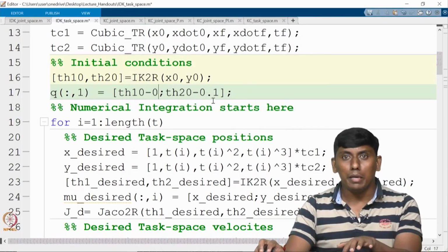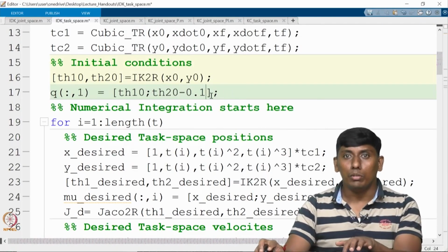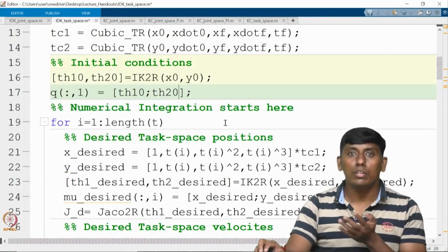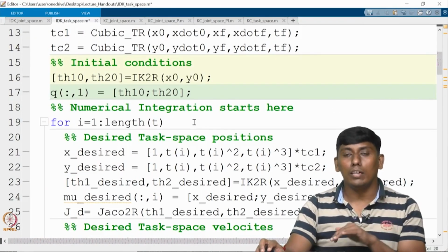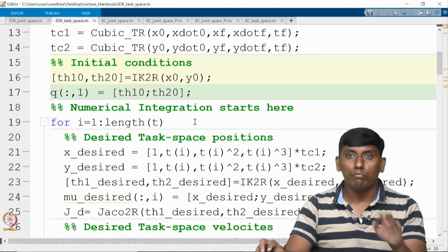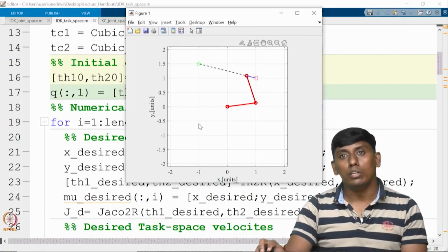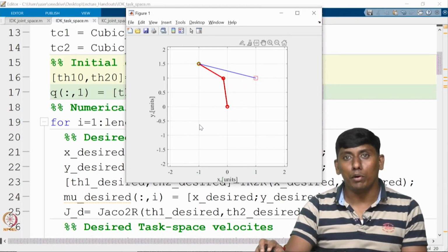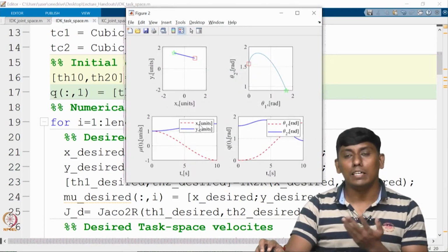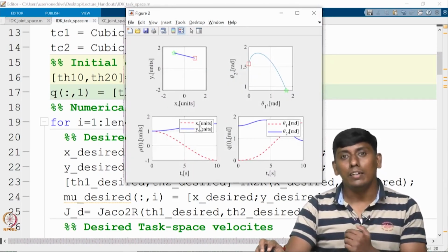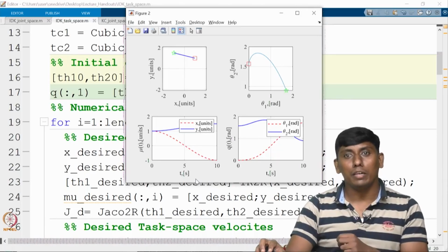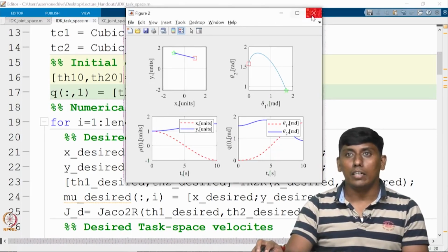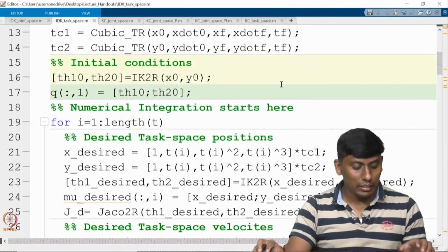So now, the condition you have seen is this, right. If the velocity is non-zero and the initial actual and desired positions are the same, then you will find that this would be a good control. That is why we call it open loop control, because it is feed forward, right. There is no compensation for the actual case. So even if I introduce a small friction or some kind of uncertainty, it will not follow the profile. That is what we want to get here.